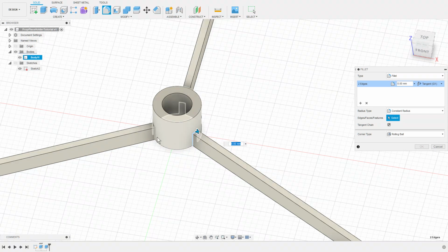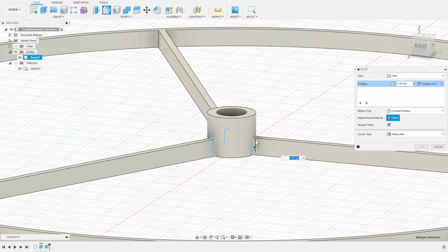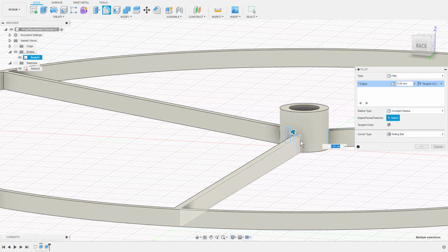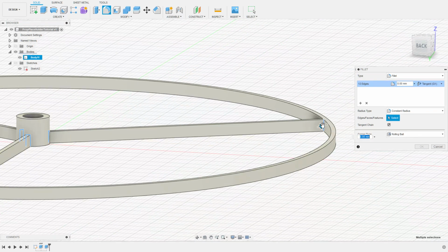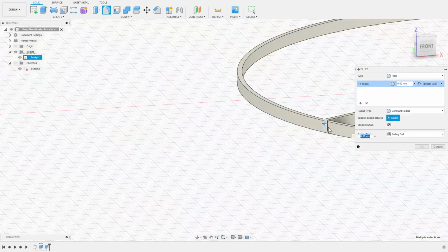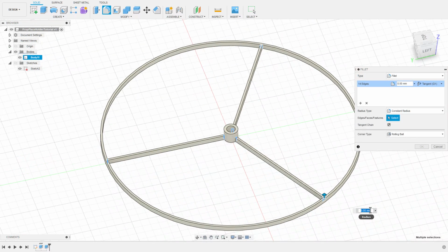And when you're selecting everything the first time, you don't technically have to hold shift, but I do like to, since you will have to hold shift or control as you do multi-selections pretty much anywhere else when you're not doing initial selection. We should now, in our radius, be able to say we are looking for our fillet standard radius and hit enter. Oh, there was a problem.